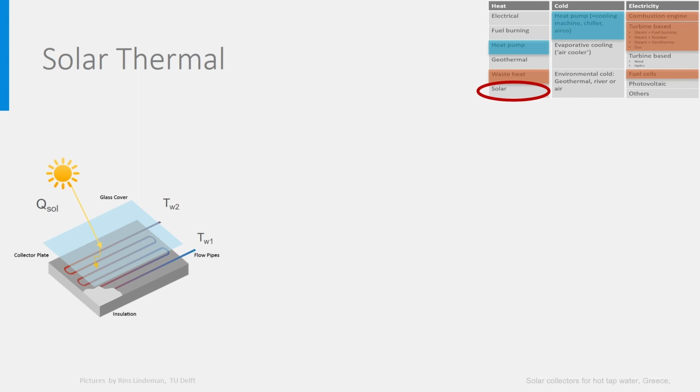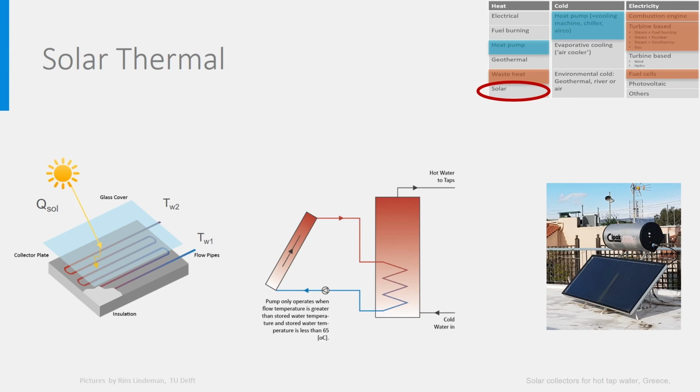To deal with the intermittency of solar radiation, we can use a storage tank and fill it with hot water when the sun shines. In a system with a tank, cold water is fed underneath and a heat exchanger with water coming from the collector heats the water. Warm water rises to the outlet, from the outlet pipe to the taps, and the taps are located above.